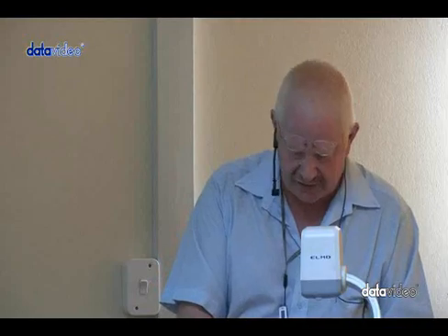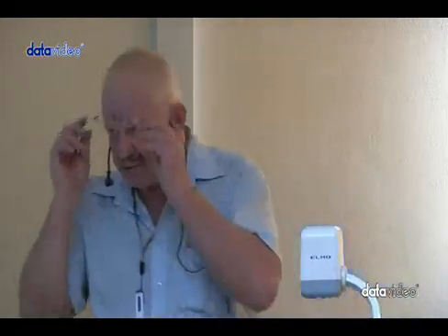All right, also alpha AC, HFB, and then on the next page you can see I can use the H parameters to determine the R parameters. But we're not going to do that. Just know that it is available if you do need it at some stage in your career. But of course we're going to determine r'e by that standard formula of 25 millivolts divided by IE. So we stick with that one.